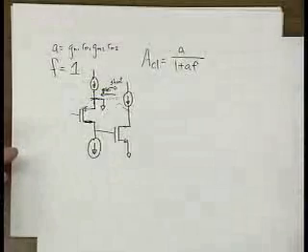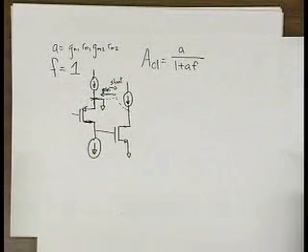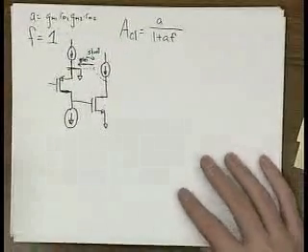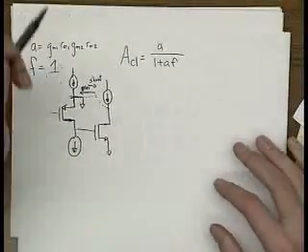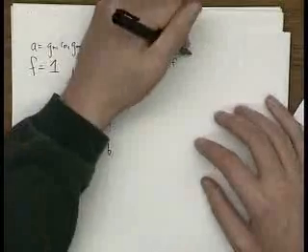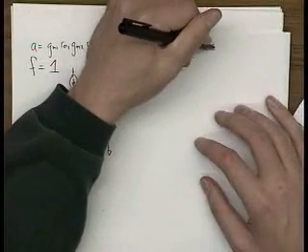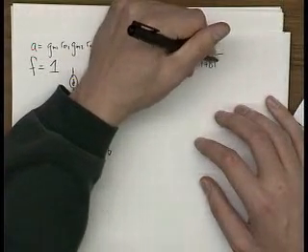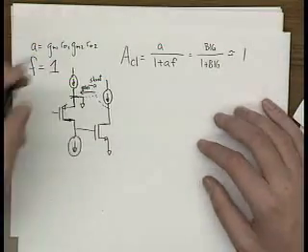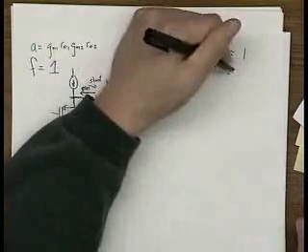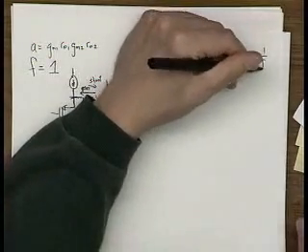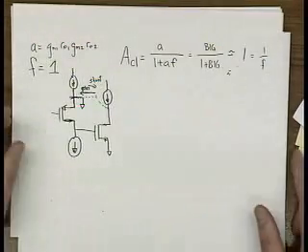It makes things tricky, but that's the way the math works out. So getting back to the mathematical analysis, the closed loop gain is equal to A over 1 plus AF, which is basically a big quantity over 1 plus a big quantity, equal to 1 over F, as we expected.